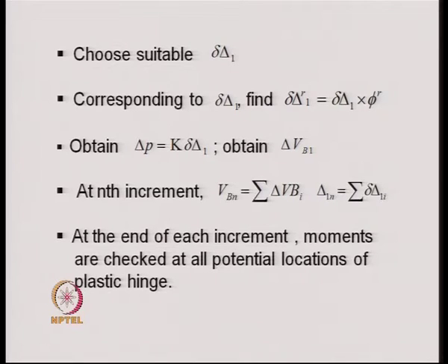Corresponding to this delta delta 1, we find the incremental displacement at different levels of the frame, that is, for the rth level, delta delta 1 r is equal to delta delta 1 multiplied by the mode shape coefficient for the rth floor.